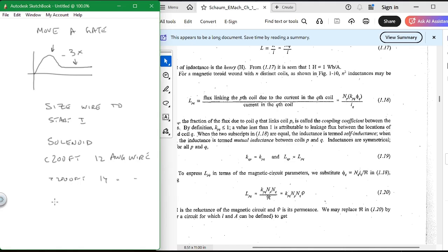But if you go beyond 200 feet, why would that be a situation? Because what does the current have to do? It has to go out to the solenoid, and the symbol for a solenoid is this little device like that. Then you have to come back, don't you? You have to go 400 feet. And then the ohms per foot, where do you get that from? From the National Electric Code, don't you? The National Electric Code says so many ohms per foot for 14 gauge or for 12 gauge. And now if it takes 90 volts for this to turn on and you start with 110 volts, you need at least 90 here, so you can't lose more than 20 volts.